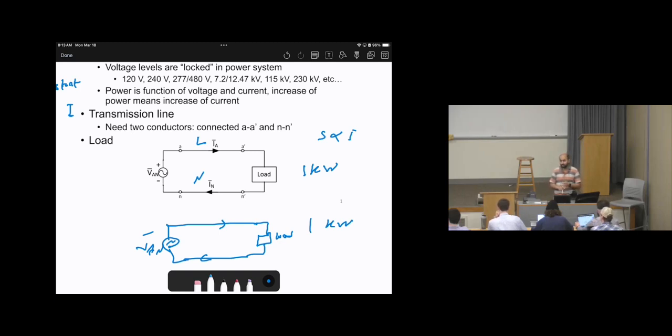And the other thing is the overall cost, because you are connecting the power lines based on the infrastructure of the towers, even the weight of the wires. So if you increase the thickness, this will increase the weight and affect the mechanical structure of the towers. So it can be very expensive because we need to modify all of the power lines and utility poles so they can handle that larger thickness. So yes, it's also a good idea to increase the thickness, but unfortunately it will be very expensive.